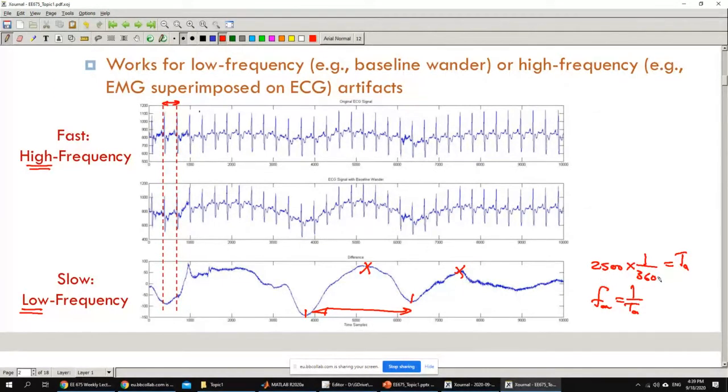You see here, this will be about 250/36. Just get a very rough estimate. This is about 8. So 2,500 over 360 is almost 8. So the frequency is about 1/8, which is about 0.125 hertz, of course. So if you design a filter with a cutoff frequency around that, for example 0.5 hertz, it should remove this artifact. And we saw that this was exactly the case.